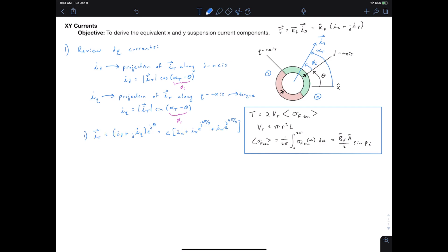If you recall, the way that we resolve this issue is that we talk about a zero sequence component. So our zero sequence or common mode current is the average of our three-phase currents at any instant of time. And in balanced three-phase systems, this is simply equal to 0. In fact, we would like to have this always be equal to 0 because a zero sequence current is a current component that appears simultaneously in all three phases and does not produce any torque and does not produce any force. So we like to say that this is always 0.